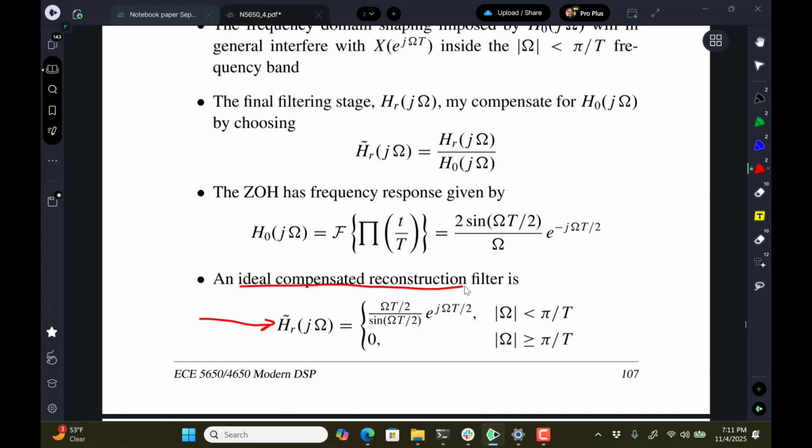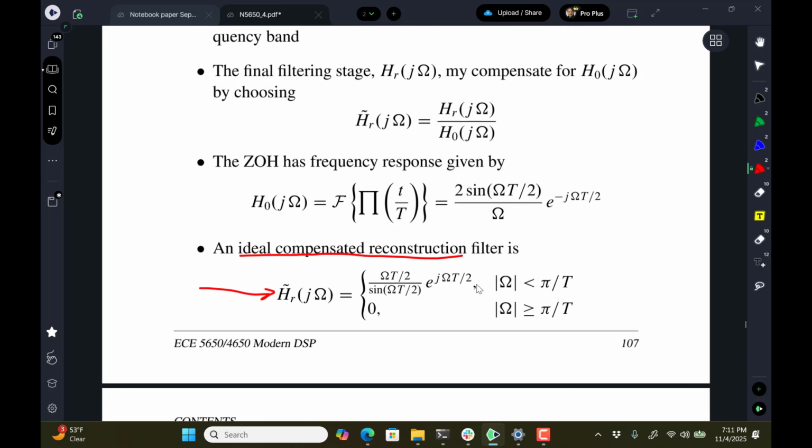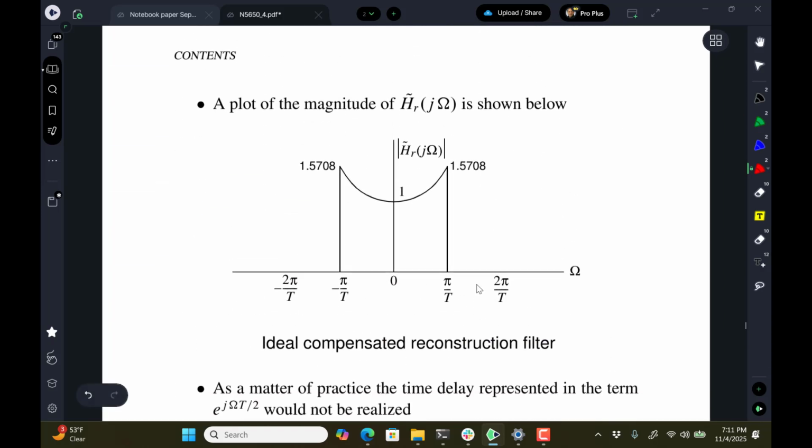And then if you could build a really high order analog filter to roll off, you'd be perfect. But of course we can't do that, so we have to settle for some realizable filter, and again, just like on the input side where we were oversampling, we oversample on the output side too, to avoid these issues.